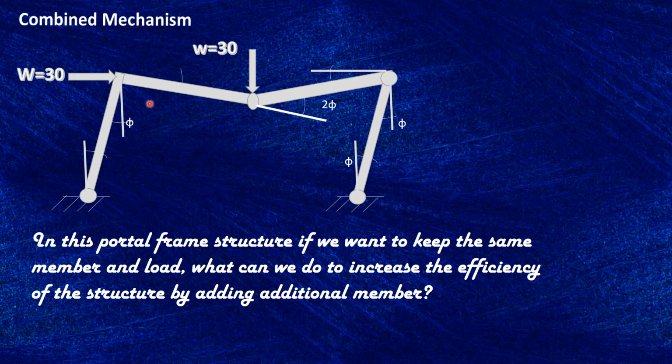We can provide diagonal bracing that can withstand this horizontal load, so that the structure can stay where it is, because we've seen that if we get rid of this load, the structure will stand. So providing the diagonal bracing is one solution.